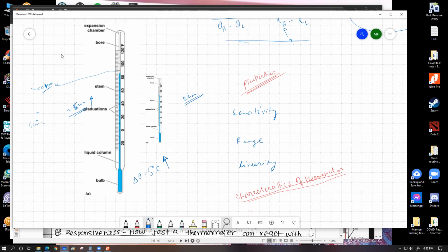If you place these lines one upon another, touching each other, that is basically going to give you a whole black continuous pattern without any gap in between, so not going to be useful. The maximum number of individual lines is 5 divided by 0.01, which is 5 into 100, 500 lines. But drawing 500 lines practically diminishes the usefulness of this thermometer, because you cannot take a reading from any of them since none of them are individually distinguishable.